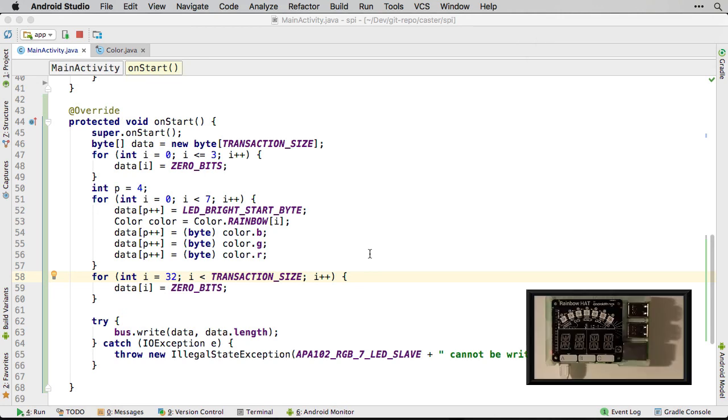That's it. You now understand how the Android Things SPI output communication with peripherals works. You can interface with an APA102 LED strip controlling each LED's brightness and color individually but updating simultaneously. This knowledge also transfers to other SPI peripherals such as other types of LED strips, pressure sensors, potentiometers, or graphical displays.